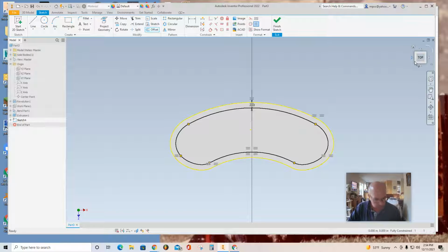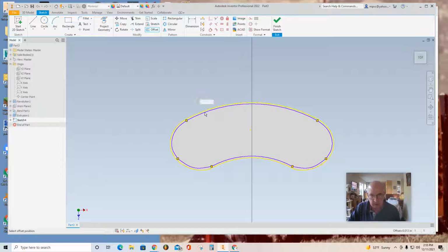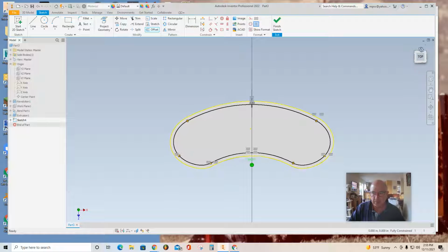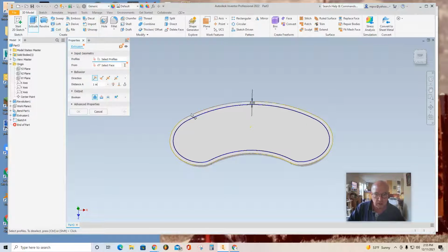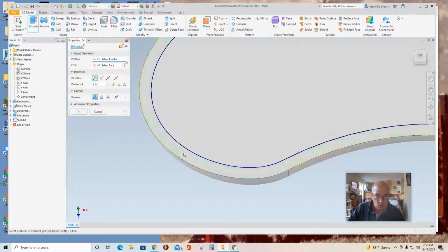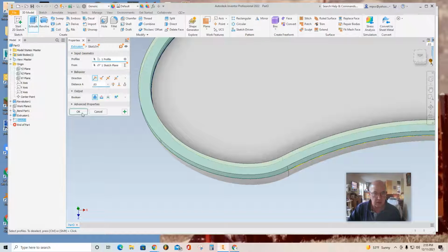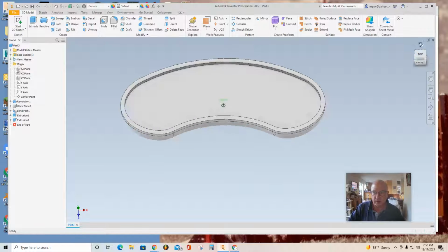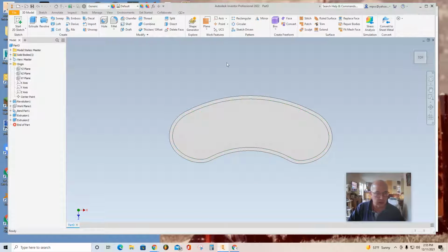Maybe that's okay. It could be a little thick. You can always go Control Z and try that again. Let's see what happens. Yeah, maybe 0.03. Enter. That's about right. Your sketch and extrude. You can just select the wall portion that you want, and also shouldn't be 1 inch, but maybe 0.03 again. There you go. There you have a nice model of a mitochondria.